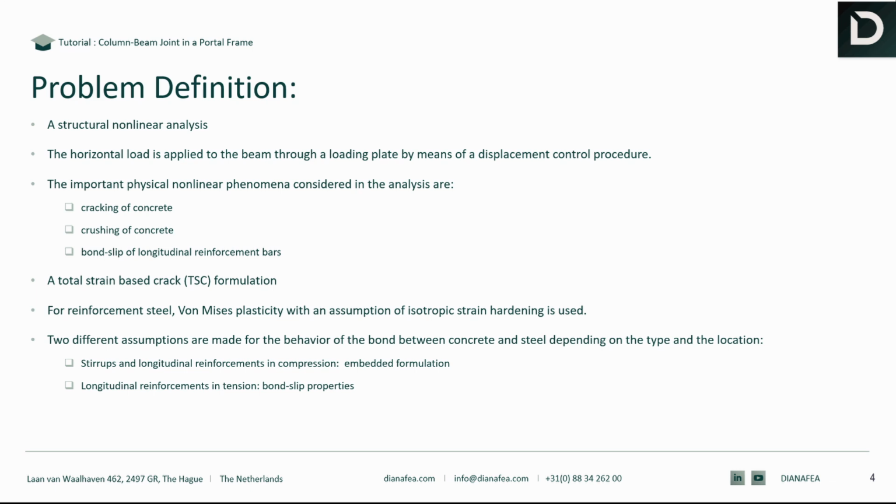Now I want to describe the summary of the problem definition. In this problem, I will focus on the structural nonlinear behavior, including both physical and geometrical changes. The horizontal load is applied to the beam through a loading plate using the displacement control procedure. The main physical nonlinear behavior that I want to consider is concrete cracking, concrete crushing, and bond slip between the